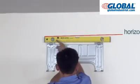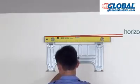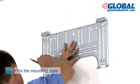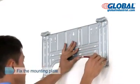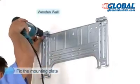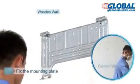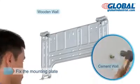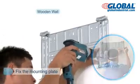The wall board should be inclined appropriately according to the position of the drain pipe. Align the screw hole corresponding to the mounting plate with the plotted position of the screw, and plot the positions of several other screws. Fix and install the siding after the installation position is confirmed. If it is a cement wall, insert the plastic sleeve first, and then fix the installation plate with tapping screws.